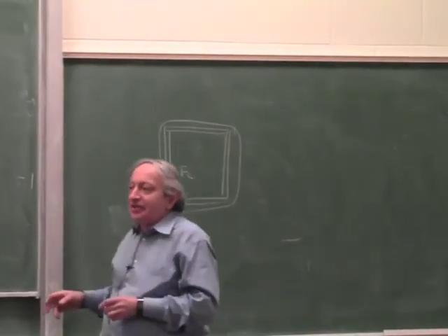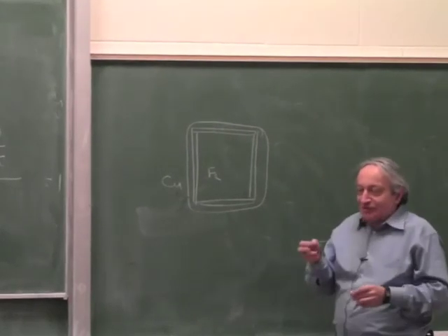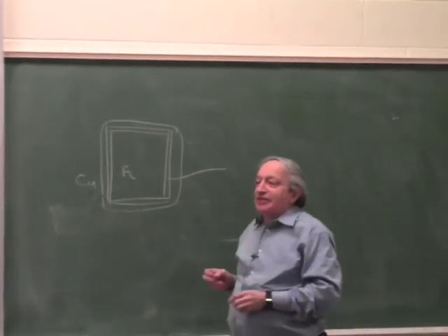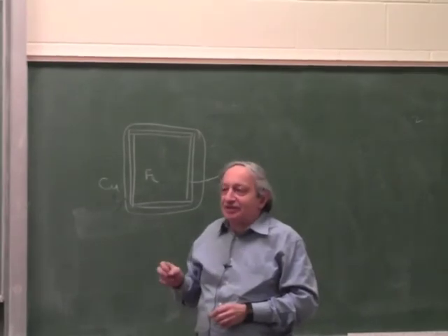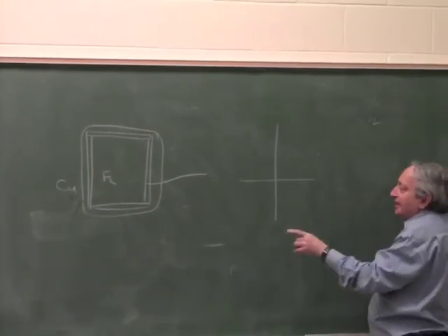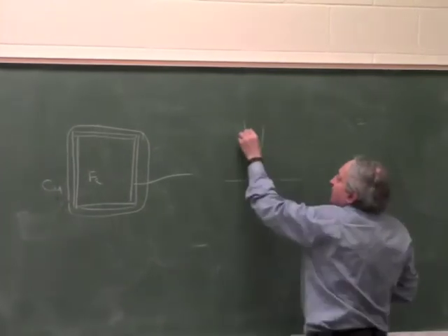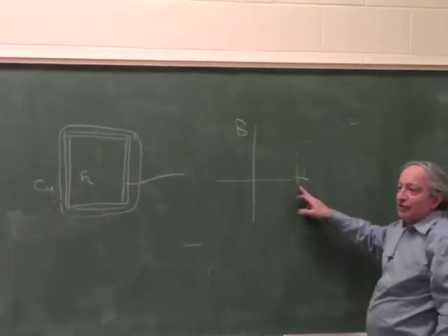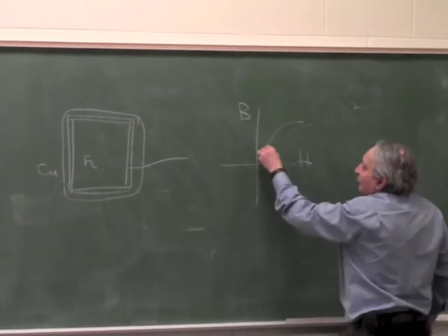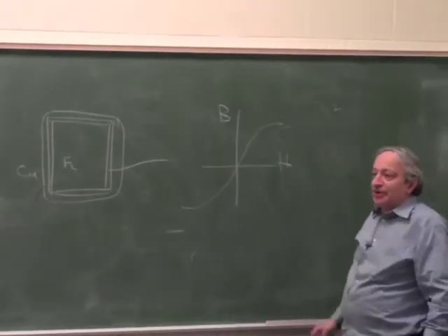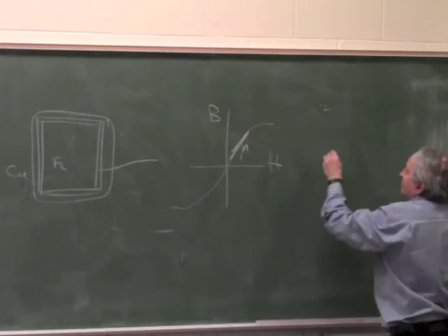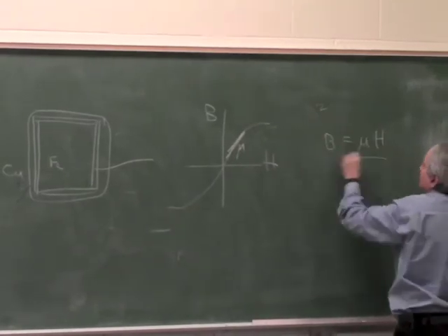So that's a classical way of doing it, and for the connoisseurs, for the people who really like to do a very good job, you don't use steel, you use an alloy which has a very high permeability even at low fields. Because it turns out if you look at the graph of steel, magnetic materials are characterized by a graph which is called a BH curve. H is the magnetizing force and B is the resultant field. Typically you've seen these graphs, they look like this for all materials. We'll talk more about it when we talk about actuators. So that's a typical BH curve, and this is a slope. The slope is mu, because as you recall, B is mu H. That's the definition of B.